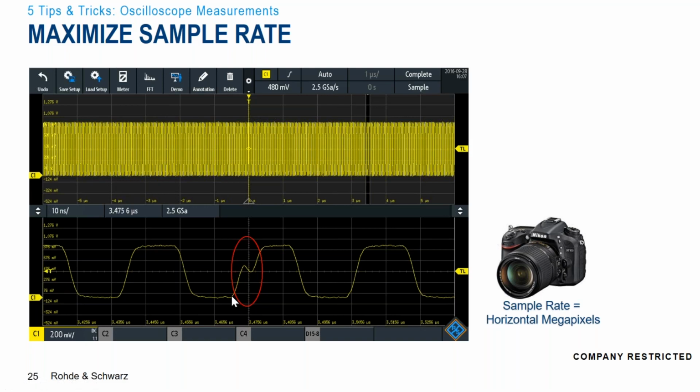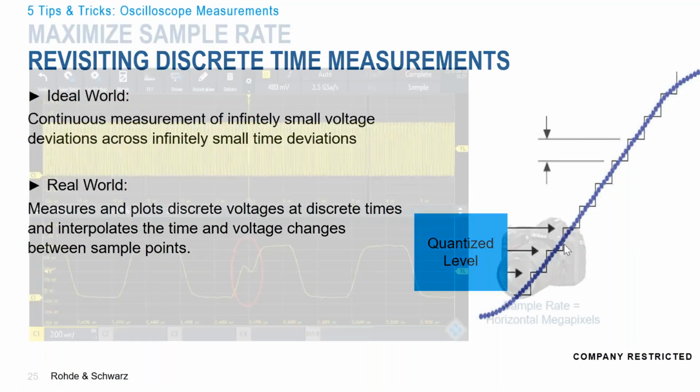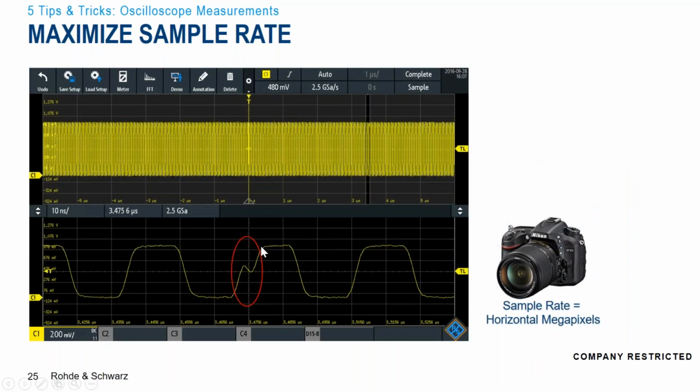So it's often confusing when we see these perfectly connected lines on an oscilloscope, but on this previous slide, we see discrete data points. So what happens is an oscilloscope might take a measurement here and take a measurement here and interpolate, or connect the dots, in between. So if you don't have enough sample points to indicate that there is an interesting transition, like here, the oscilloscope will just simply connect the dots from the lower end to the higher end. And there's more behind it than that. There's sin x over x interpolation or other types of algorithms. But what the oscilloscope is actually measuring is a discrete data point. So on most oscilloscopes, you can go in and actually show the data points versus the interpolation. We can take a look at that on the oscilloscope when we switch back over. But it's important to remember that the scope is measuring discrete data points.